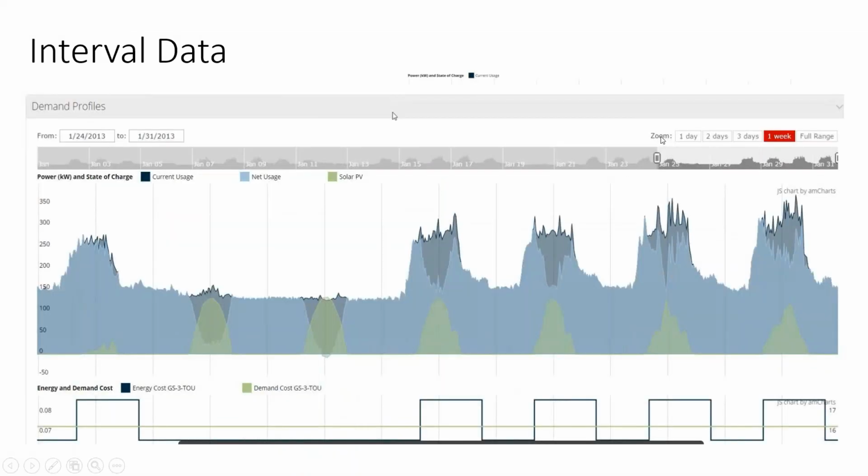In fact, where I think that this is going to go is basically to say that flooded lead acid technology is really good for running a building's base load, and then you might want to have a more expensive lithium ion technology take care of these peaks.